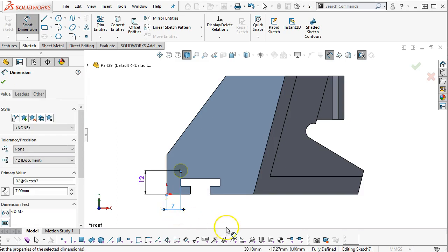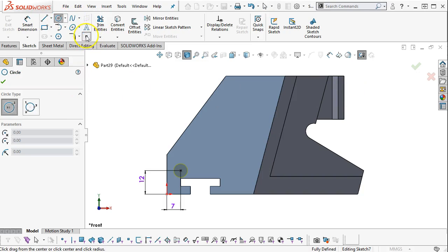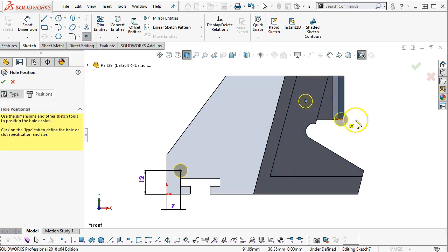So that doesn't look close to the perspective either, so what did I miss to center line? Yeah, maybe that wasn't center line, that was the other hole. So, 2015. That makes it even closer. So that's got to be a 25. Yep, that's going to be a 25. So 7, 12. Alright, so that's good. We'll pick that one up. Jump back in to our depth, 6 millimeters off of the edge.